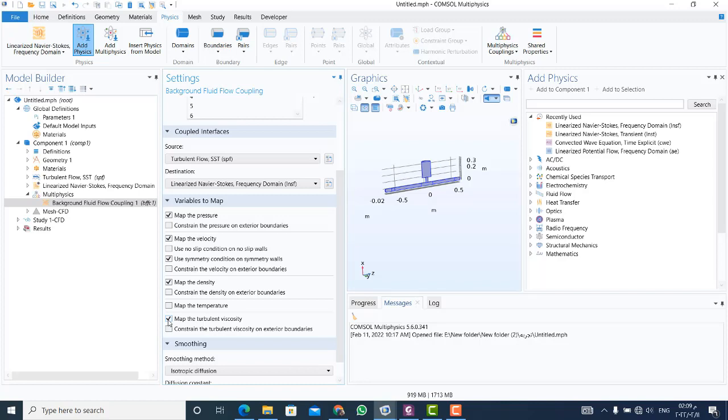Okay, and then we create the acoustic mesh that the CFD solution is mapped onto. The mesh can be relatively coarse. Note that the finer the mesh, the less damping is introduced by the stabilization that is present to stabilize sub-mesh physical phenomena like velocity waves. At the wall, we don't resolve the acoustic boundary layer since slip and adiabatic conditions are used here. One or two boundary layer mesh elements are enough to resolve the background flow profile near the wall.